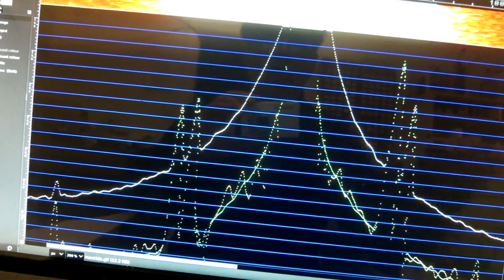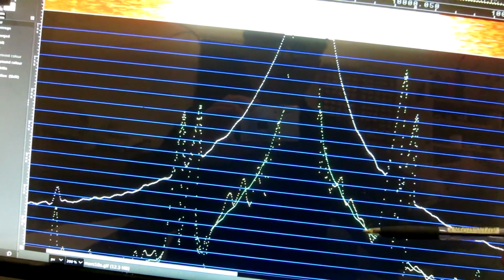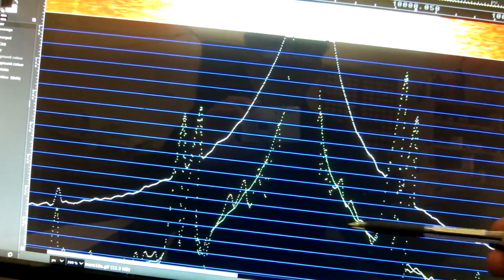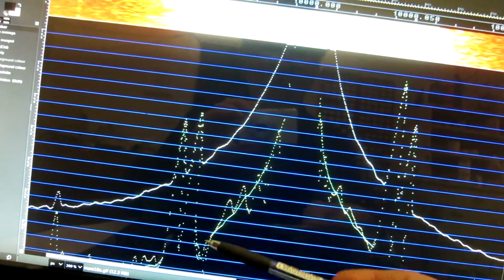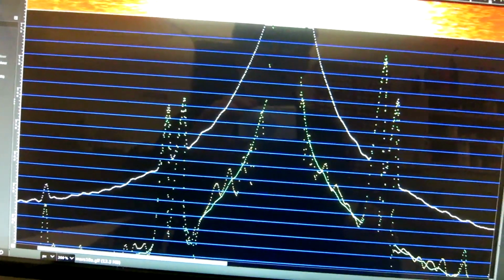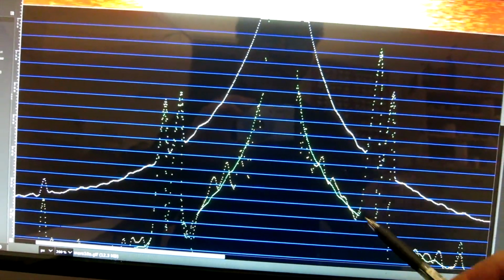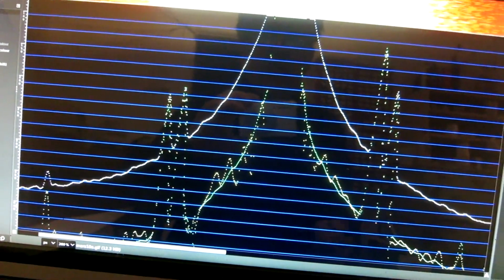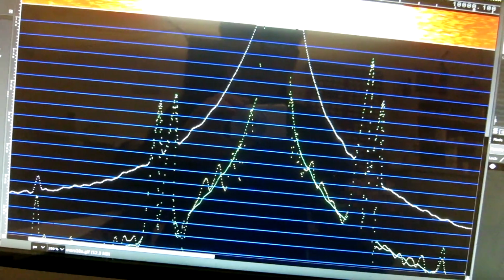And I can see that the noise on the high side, here about this separation from the spur, is much higher than here at the same separation from the spur. So if the noise has an origin similar to the 50 Hz sideband, then it's natural that it's stronger on this side than on this side.